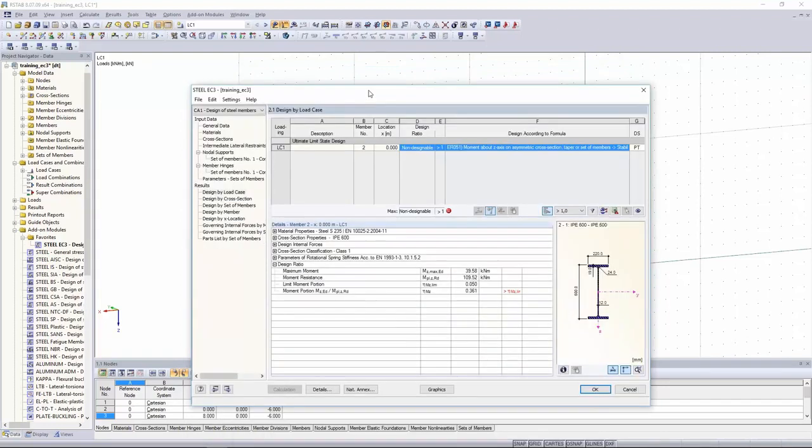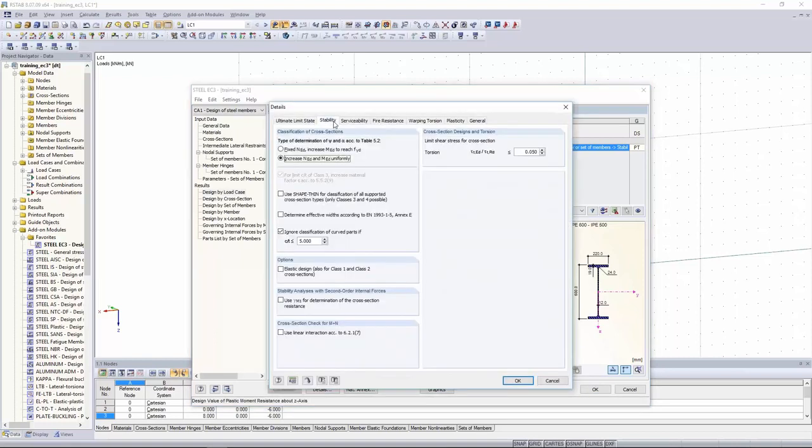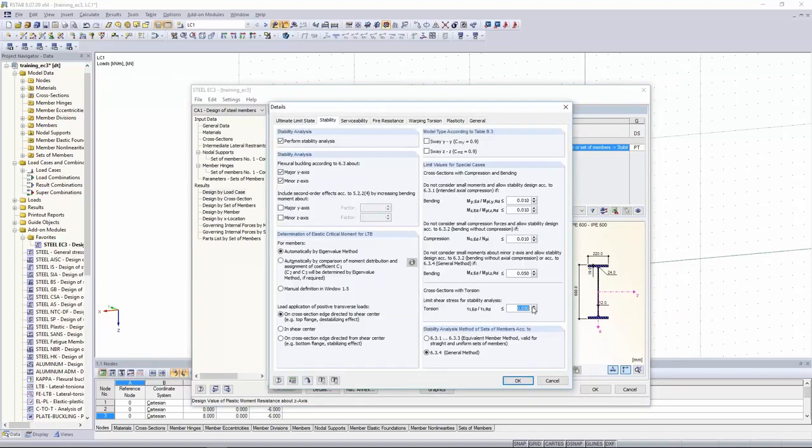And there's one really easy solution in Steel EC3 now with this new module Warping Torsion. You can see over there we have quite a lot of cross-bending with about 36% of the resistance and plastic. So we cannot say, okay, I want to neglect, let's say, 10% of the cross-bending over there.